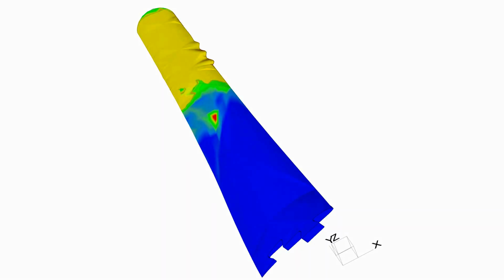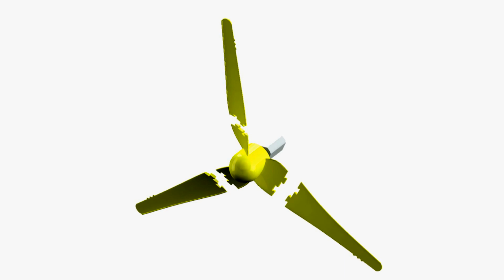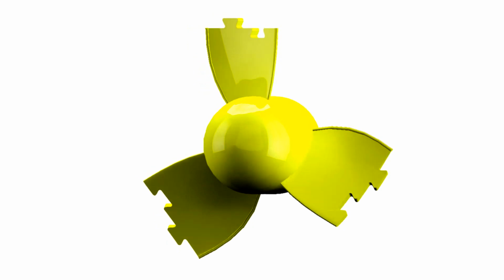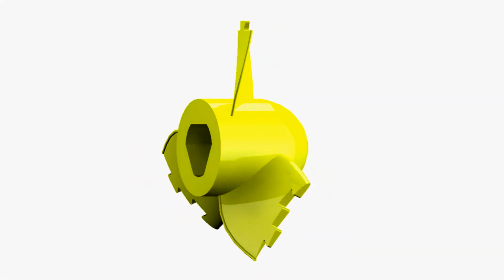A maximum stress, therefore, of approximately 1.68 megapascals was found, well below the yield stress. Since the rapid prototyping method only produces designs no longer than 195mm, we split our turbine into two parts. We chose a trapezoidal shaped jigsaw joint with rounded corners to ensure significant interlocking between parts and minimise the stress concentrated on joints. Next, we used a simple half sphere for our cone design to ensure it is streamlined.